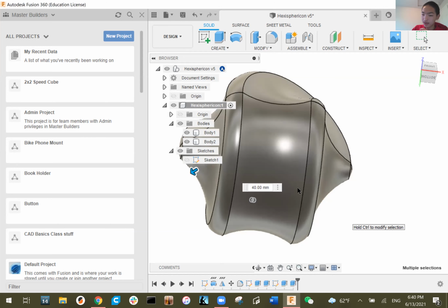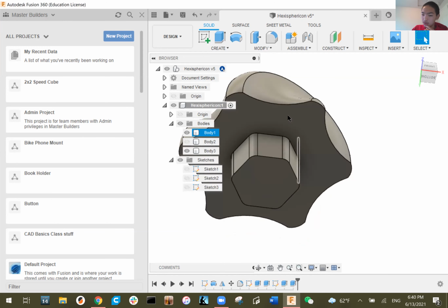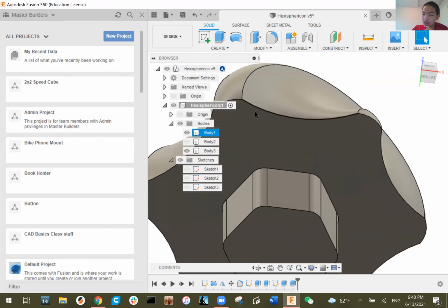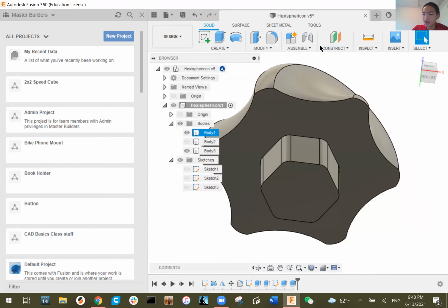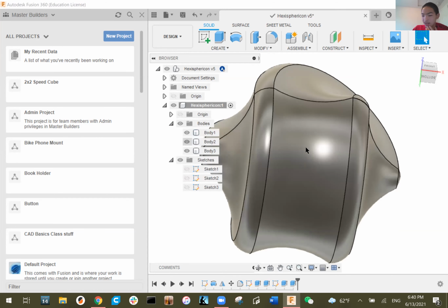If you highlight over it, there should be some white highlight around it, and then you can click on it. If you bring your cursor away, it will show up as light blue. Then you can do that with all the edges, and then you can fillet them. You have to do all of them at the same time. All right, does anybody have any other questions so far?